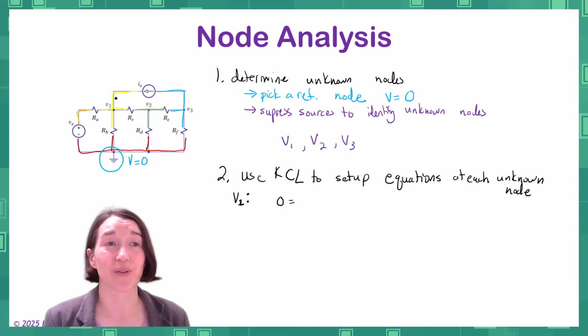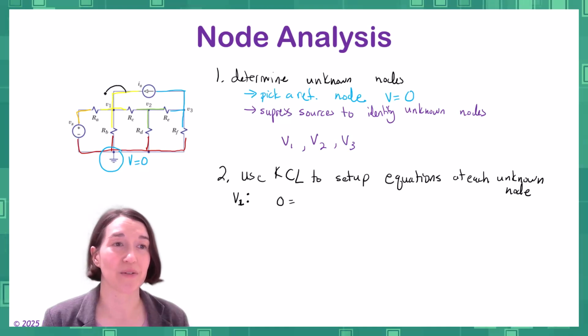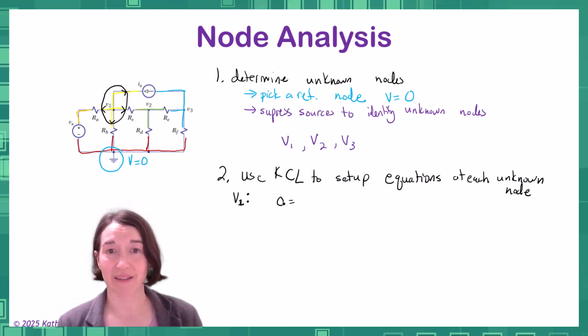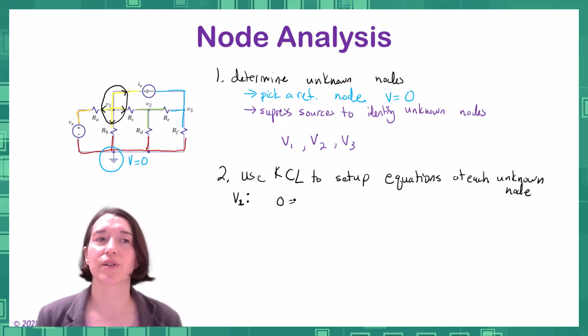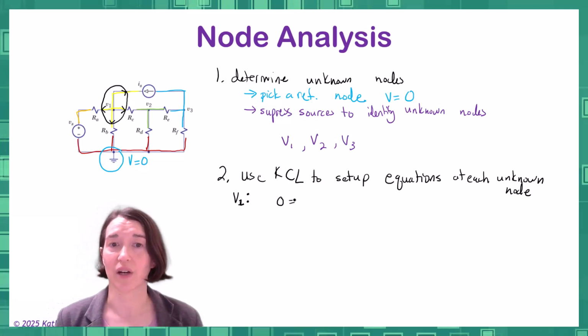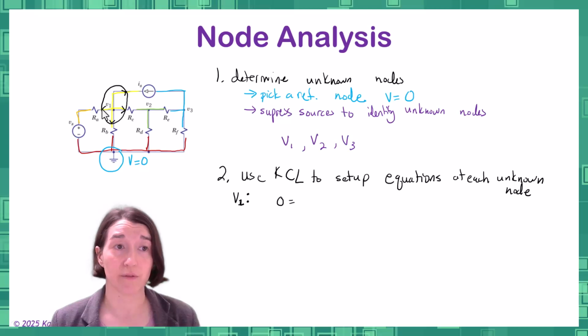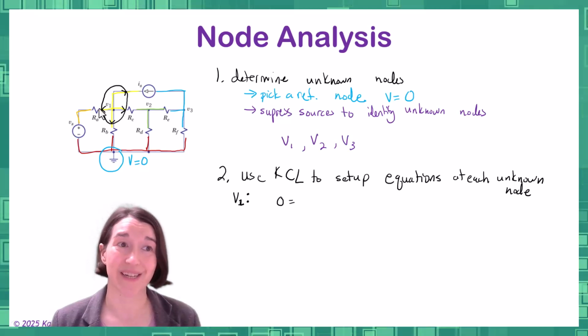We are going to use current out of this node, and I will draw it this way. So current going out here, out here, out here, and then we're setting up the KCL for that. We're going to do each of the equations for the current out of the node. So the first one is going to be the current branch out here.